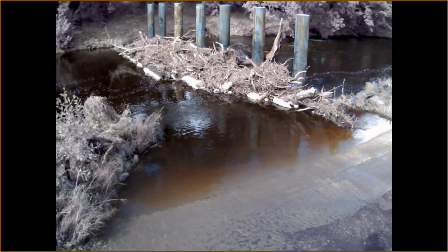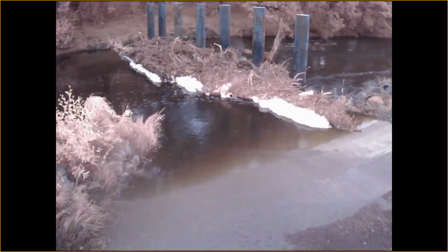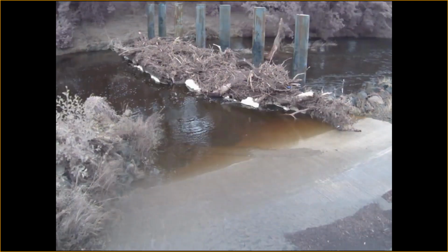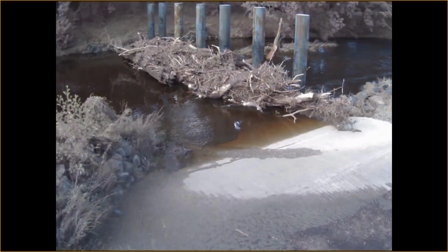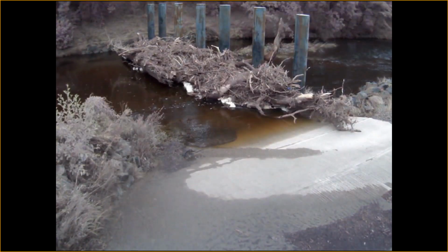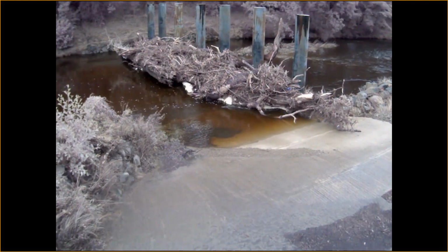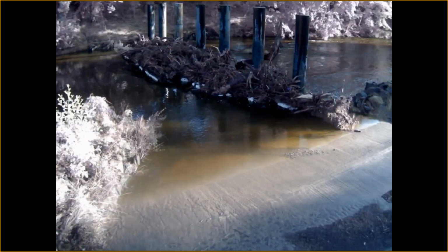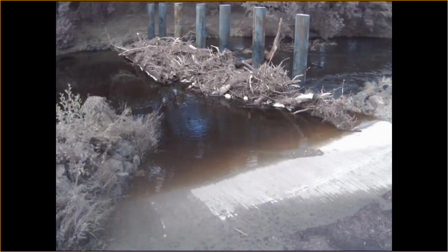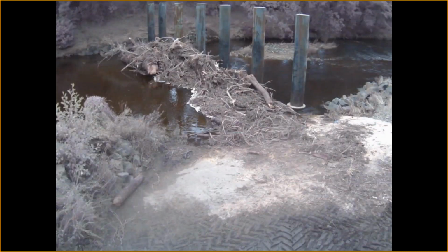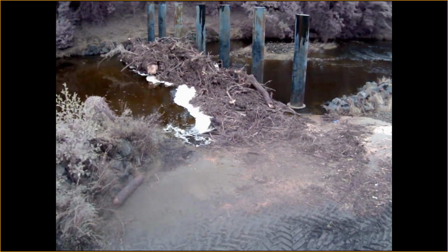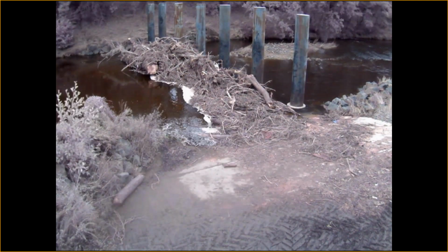And now you'll see the operation to remove the debris. Now, screens generally are not designed for removal of debris during a high flow event. They need to be designed, though, for removal of the debris as easily as possible once the water levels have dropped. So you can see here access has been made through a concrete ramp and a working area to get into the channel.